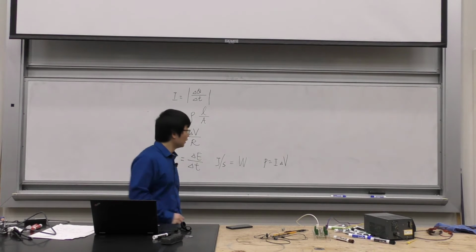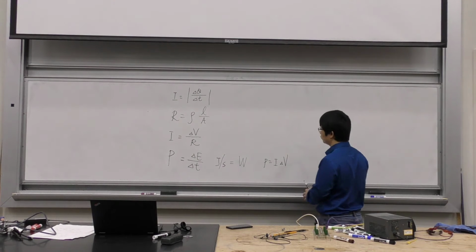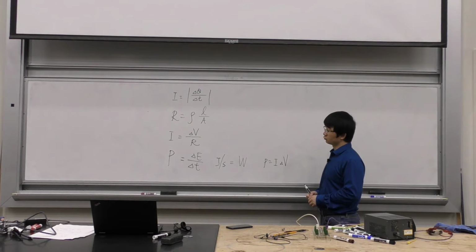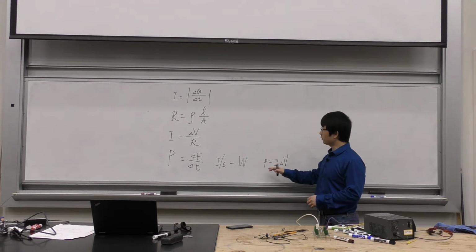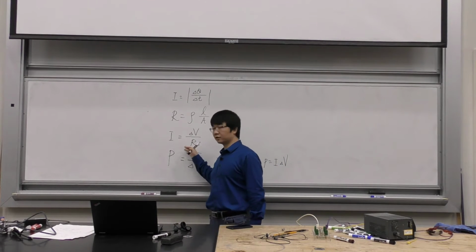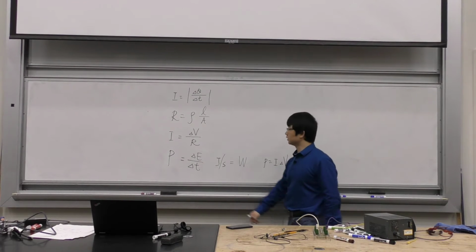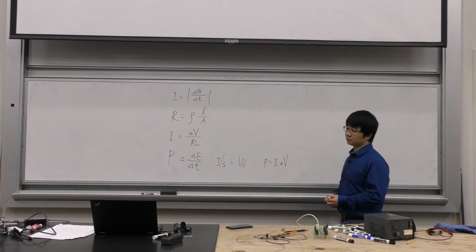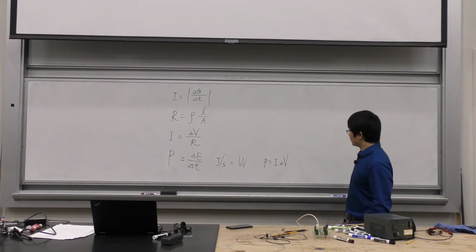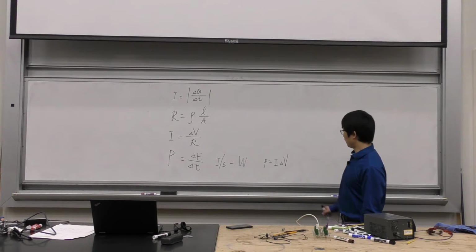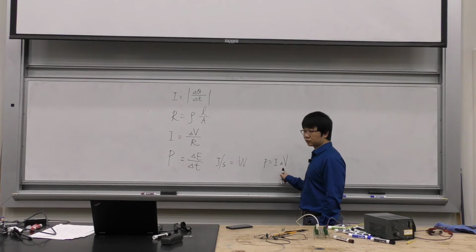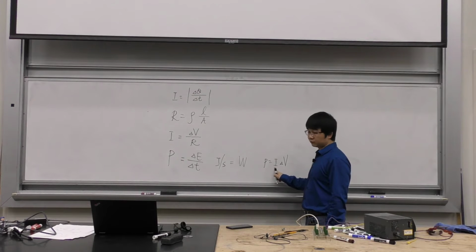Okay, so let's see. This is how power is connected to current, voltage, right? But this equation doesn't have any resistance. But remember, resistance and current and voltage, they are connected, right? So that's pretty much the most used law in electric circuits, right? Whenever you don't know what to do, try Ohm's law, okay? So actually what I can do is this, right? I already know the rated voltage of this hair dryer. I only need the rated current. The current through this dryer when it's connected to this 110 volts, right?